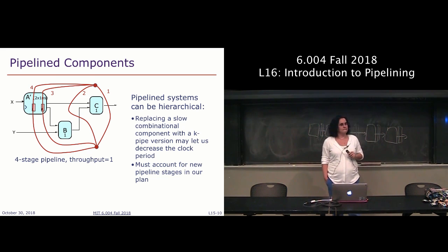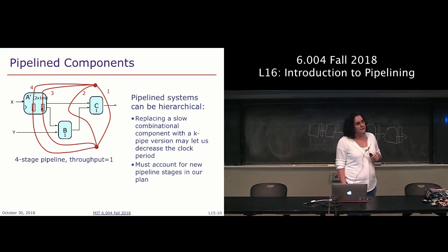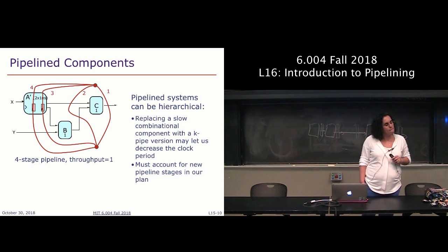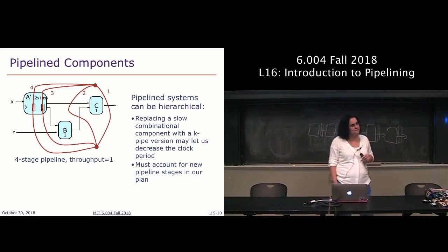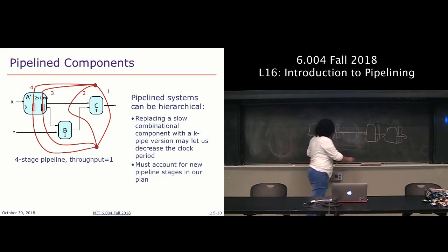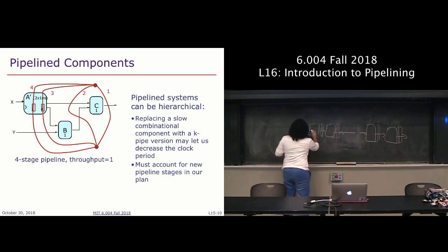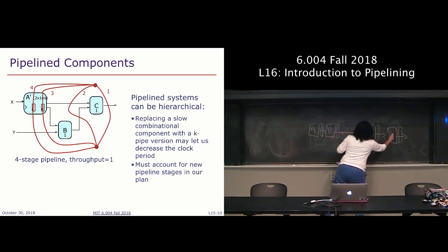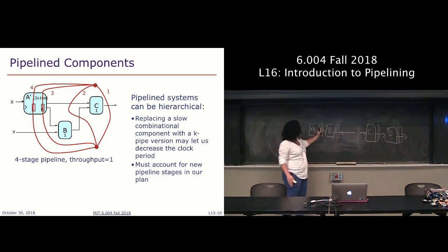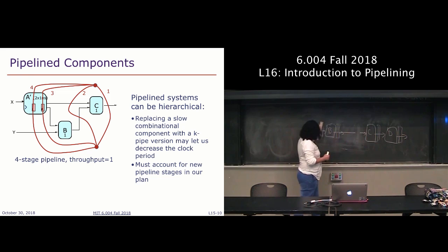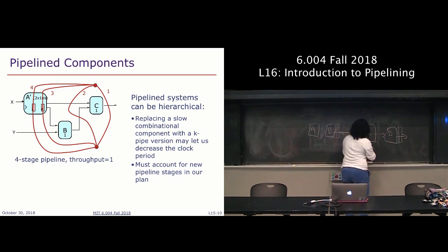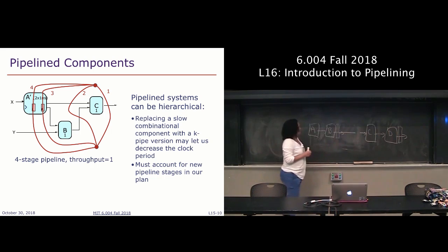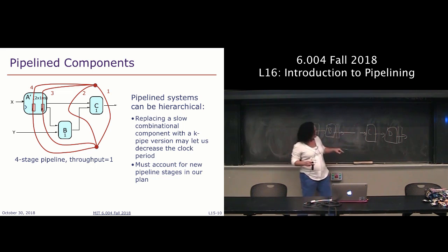Good question. Yeah, used on composition convention. So you're saying that every register has a register on output? Yeah, so this is what I was trying to show here. It's a little hard to show, but if these are your modules, at every stage of my pipeline, I'm going to have a register which corresponds to that separation between the stages. So I could have something that looks like this, where each of these things was a one-stage pipeline. But then I can combine them because I have a register at the output here.